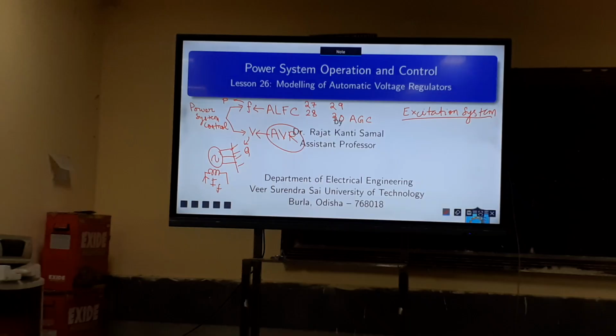The first is when the flux is stationary and the conductors are moving. The other one is a time varying flux, as in transformers. In transformers, the flux is time varying, whereas the conductors are stationary. Two conditions, so you have to use either of the two. In this case we are using a stationary flux, that is DC. It's a DC flux.